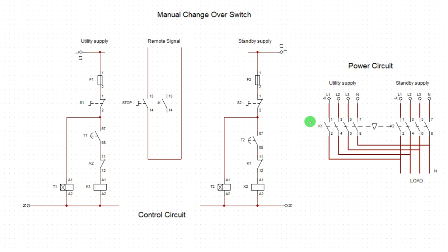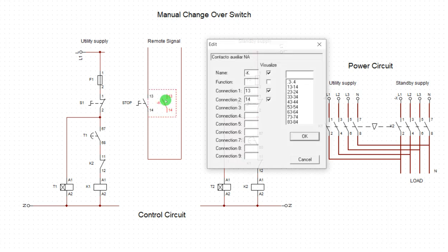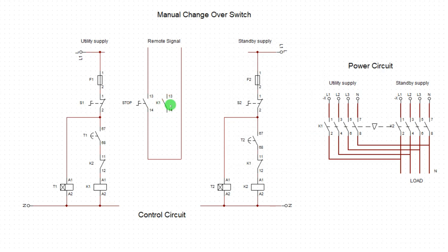We're going to run a cable from this portion, from this contactor, you run the cable and bring it here. Connect from this generator stop button to the auxiliary here. This is the auxiliary. We're going to put it as K1. Now, what is the function of this? The moment this one closes, here will also close,